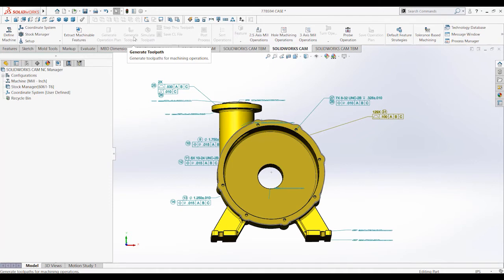So how does TBM, or tolerance-based machining, come into play? TBM is going to perform these same core functions, and it's going to use the exact same feature recognition software, but it's going to focus on recognizing the linear symmetric and asymmetric tolerances along with GD&T data, and it's going to call forth specific machining strategies we would want to apply in order to maintain these tolerances and to have our part have the best chance of passing QA inspection.